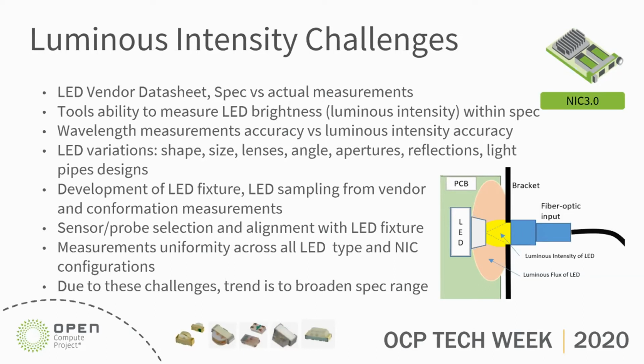For example, when you do measurements with the LEDs, you could see that there is very significant variation in parameters from batch to batch, and those variations do affect your measurements in the final conclusion for how your spec will accept those measurements or not.